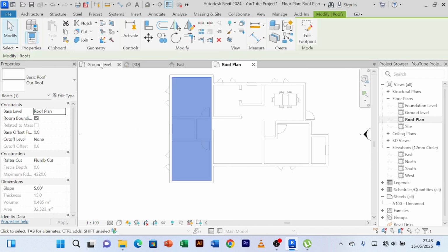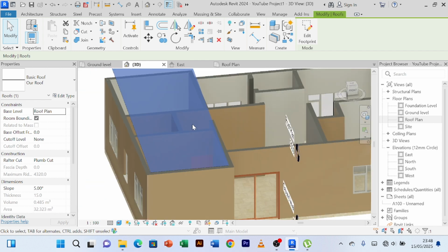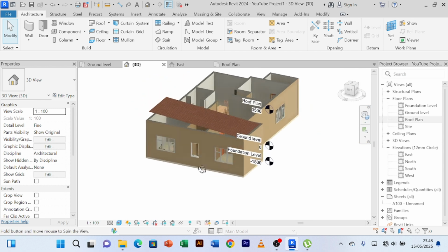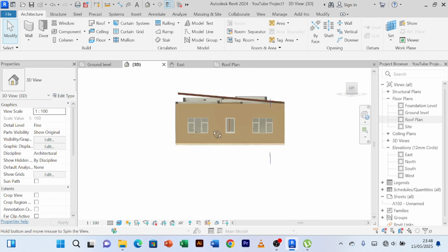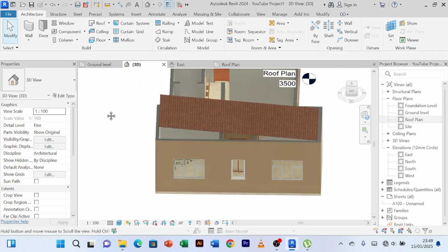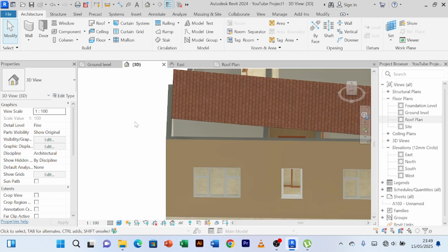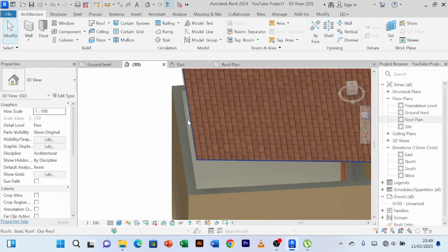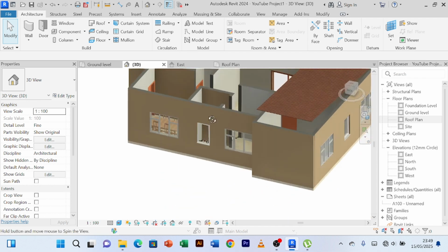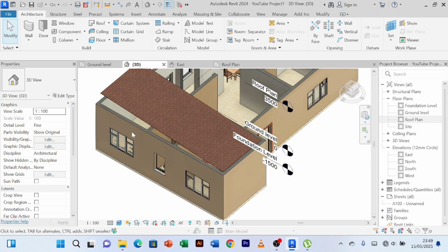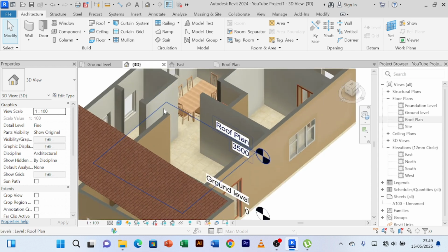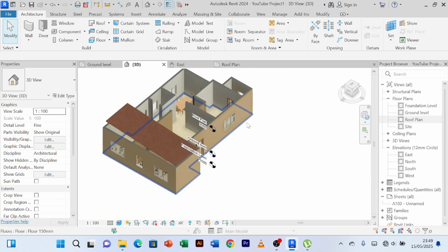Don't attach always. So when you come to a 3D, you'll see the roof is like this. You see that? This is how the roof is sloping. This is a lean-to roof. A lean-to means it leans to a specific wall. So we shall just have to draw a parapet wall here to extend it to the top of this roof so that the roof can be hidden. So I'll do this for the rest of the designs here, the part of the house.